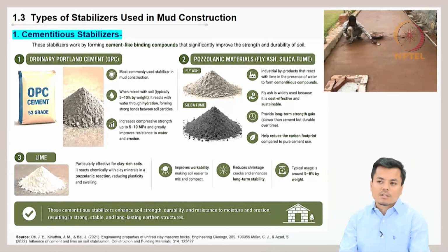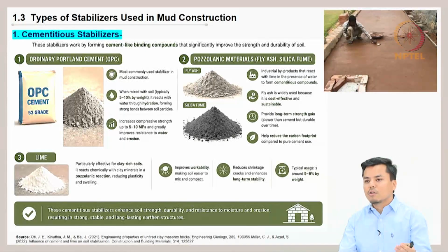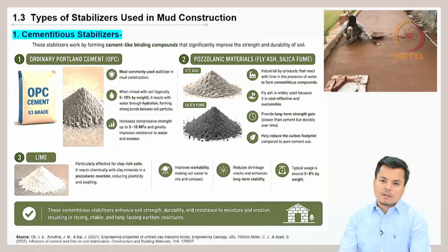It provides long term strength gain, and also it helps in reducing the carbon footprint compared to the pure cement use in contemporary building. The next is cement lime, which is particularly effective for clay rich soils where there is too much clay in the earth.